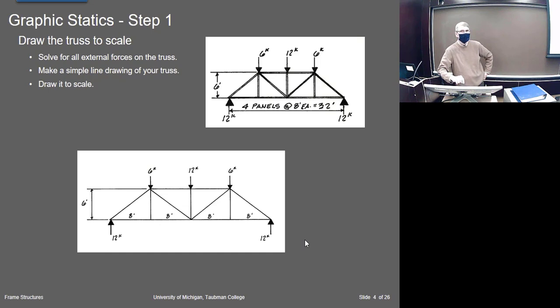First, we'll go through how to analyze a truss using this method. That's pretty straightforward. And then what you do is you do it backwards to design a truss. So the reason this works so nicely is that trusses are two-force systems, right? They're axially loaded, and the direction of the forces is exactly the same as the direction of the members.